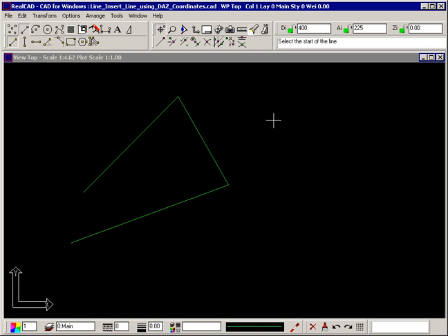To draw lines that are 300 millimeters long or multiples of 300 millimeters long, click to start the line, press D on the keyboard, type 300, and then click on the green padlock next to the D coordinate. The padlock turns red and closes, indicating that the distance is locked and all lines drawn will be multiples of 300 millimeters long. The rubber band attached to your crosshair will now jump to lengths of 300, 600, 900, etc. as you move your crosshair.